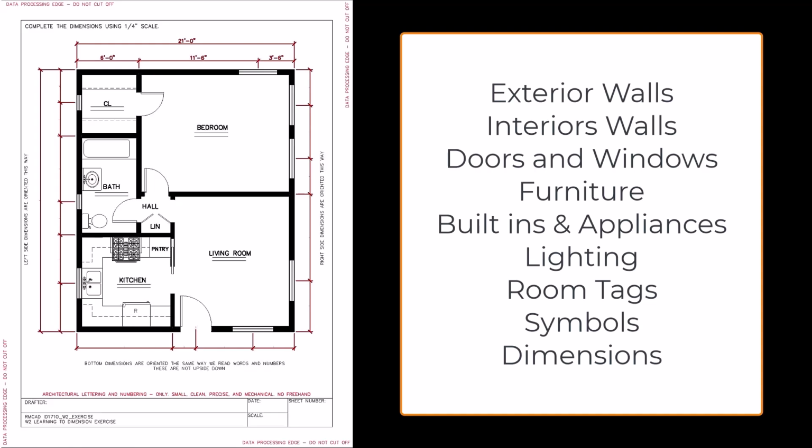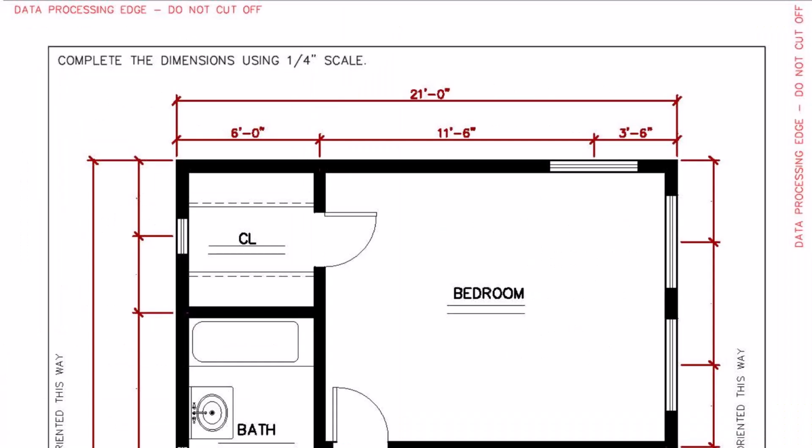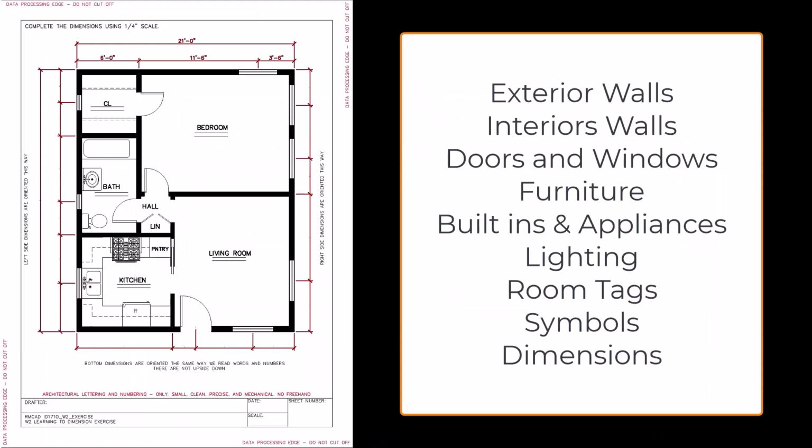So in this example, and disregard that the dimensions are in red, our door swings look exactly the same line weight as the doors themselves. And that is not accurate. We want to make sure that that swing is the lightest line weight in this drawing. We might have other things that will go in that space, symbols, etc. And so because you have to overlap that information, we need it to be the lightest or the darkest dependent on what is most important for that drawing and to communicate the correct information.